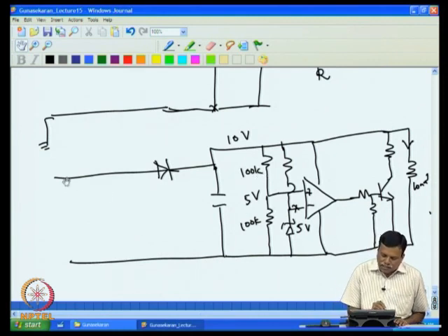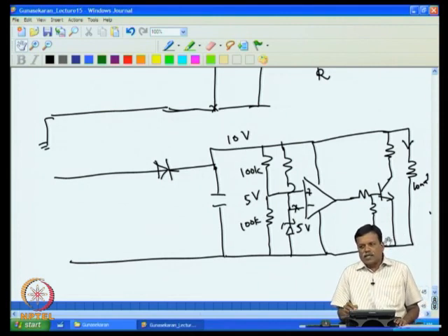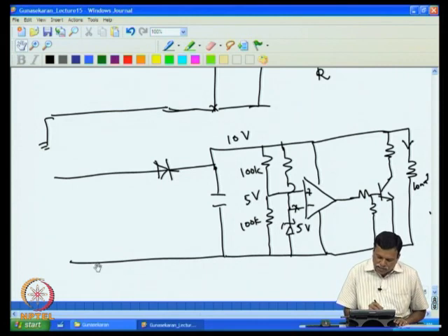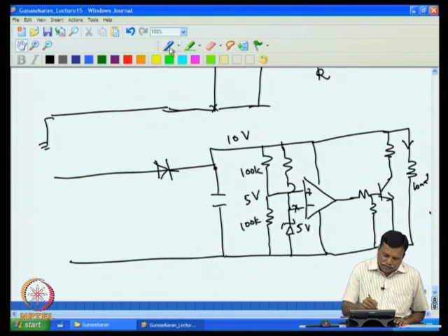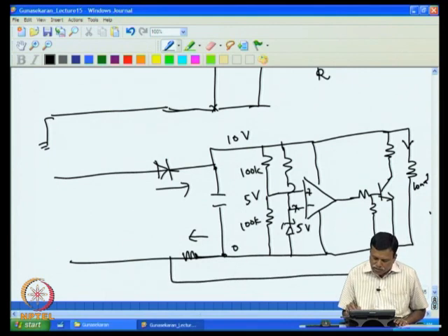So by this way the current flowing through this produces a fixed DC voltage. Now all we have to do is convert this current, whatever is flowing through that, which anyway returns to this, and this current information will provide a signal. To obtain a signal, we add a resistance here. The entire current coming here actually flows through this. So now this is our reference point, 0 volt, and the voltage at this point gives you the signal. That is V signal.